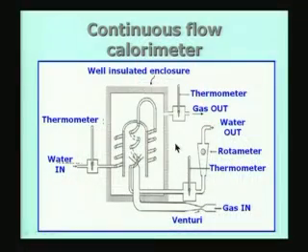The first one I take is the continuous flow calorimeter. In this case, I want to determine the heating value of a gaseous fuel. So, what is being done here is there are two components. One is the gas which is coming in, whose flow rate is measured by a Venturi. As you can see here, the gas consists of a premixed